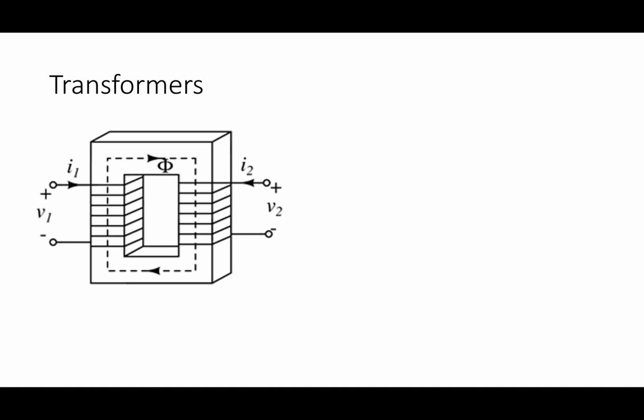Once I get the magnetic circuit, what are my sources in this magnetic circuit? Well, the coils are the sources, right? So in the magnetic circuit model, how do I represent those coils? As MMFs, right? So help me draw the circuit. How would I draw the magnetic circuit for this thing that I've shown here?